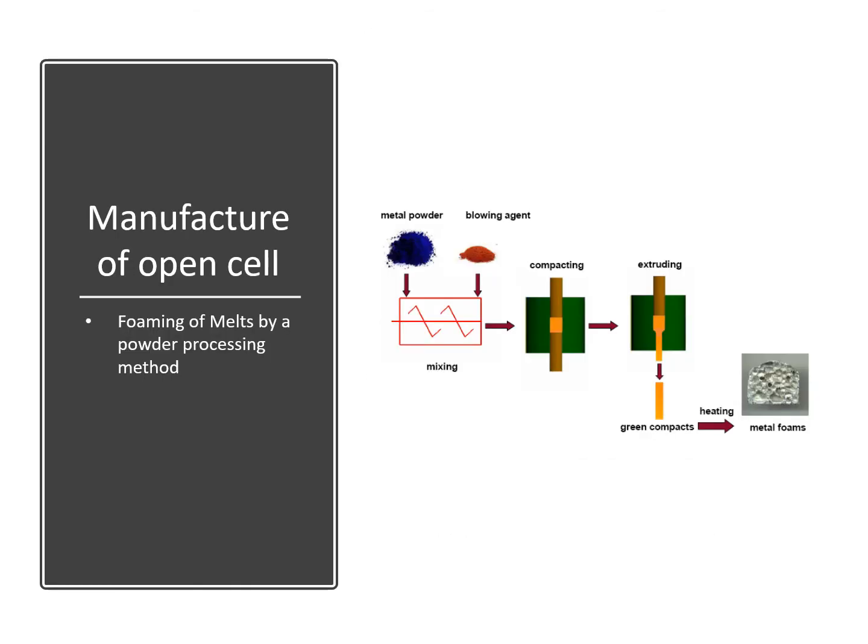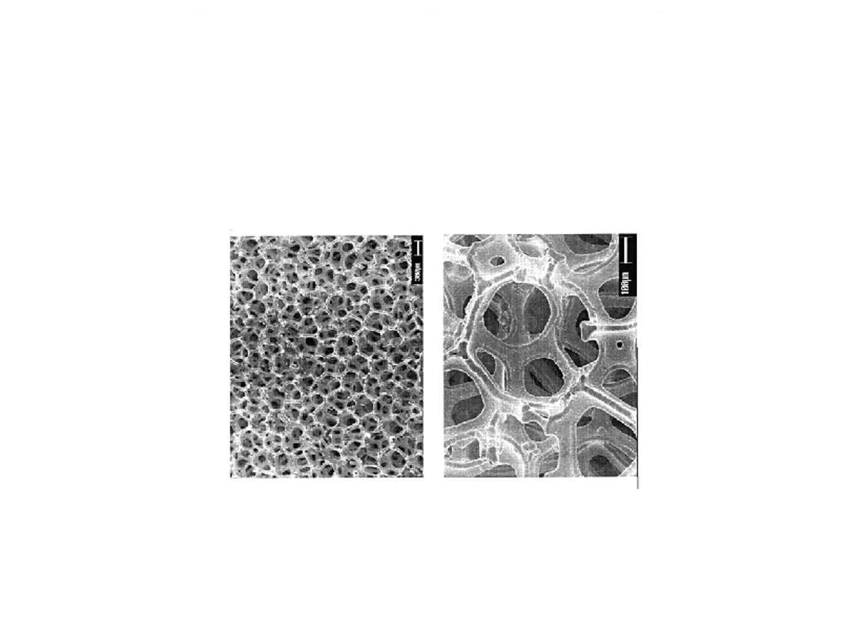Manufacturing of open cell. Open cell foams are manufactured by foundry or powder metallurgy. In the powder method, space holders are used, and as their name suggests, they occupy the pore spaces and channels. In casting processes, foam is cast with an open-celled polyurethane foam skeleton. In this picture, we see an example of an open cell metal foam.